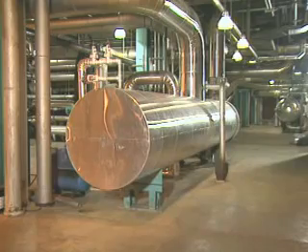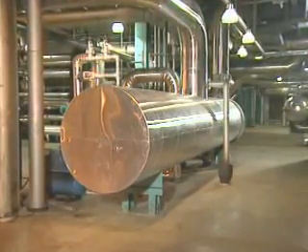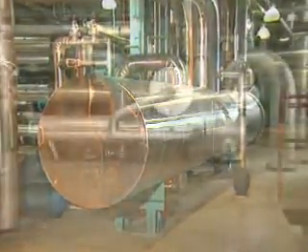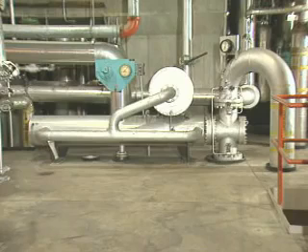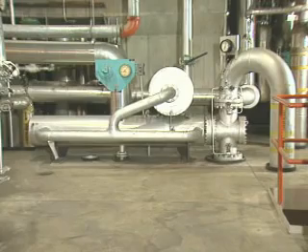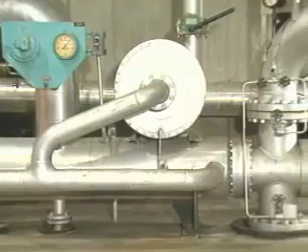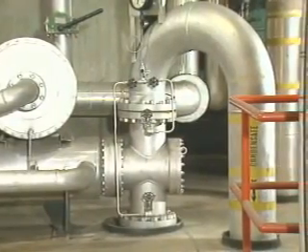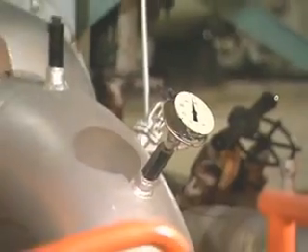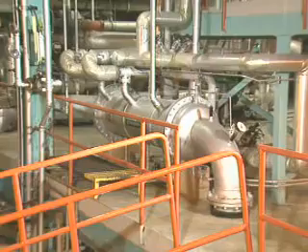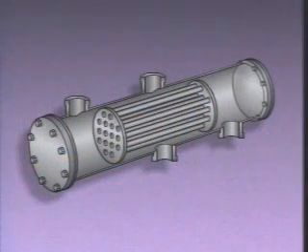A condensate and feed water system also has several condensers and heaters. Most of these are some type of shell and tube heat exchanger. For example, the initial warming of the condensate from the hot well is achieved by using the condensate as the cooling fluid in condensers. Gland steam condensers recover heat from the steam used in the plant's gland steam system. Air ejector condensers recover heat from the steam in the main condenser's air removal system.